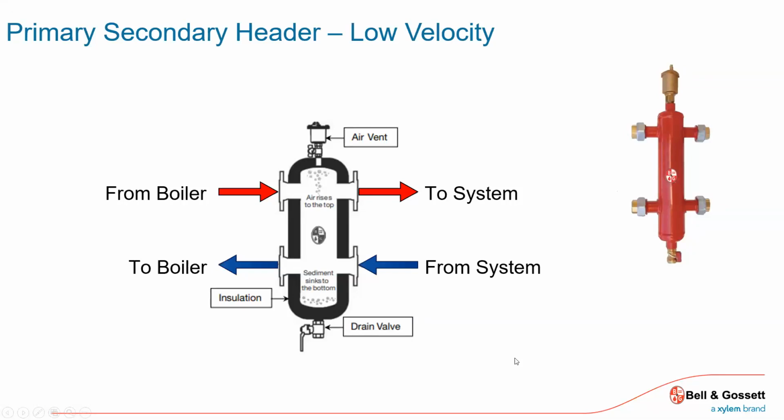And I don't ever want to see those guys fighting each other or in series with each other. So this device, just like regular primary secondary tees, will decouple my pumping on this side relative to my pumping on the system side. So yes. Correct. Right.